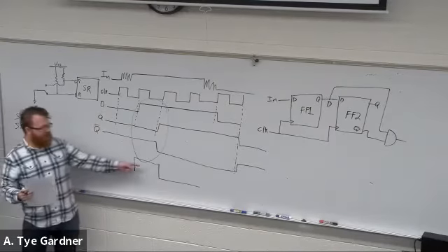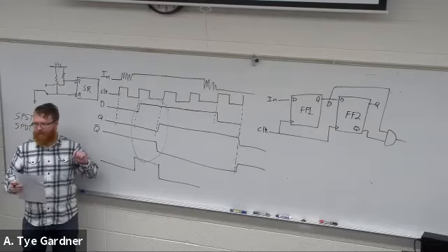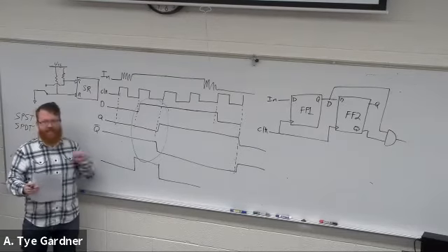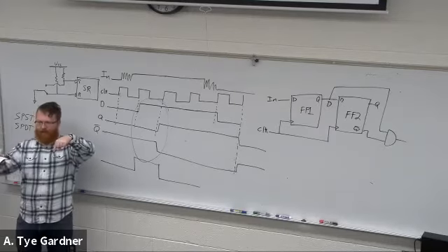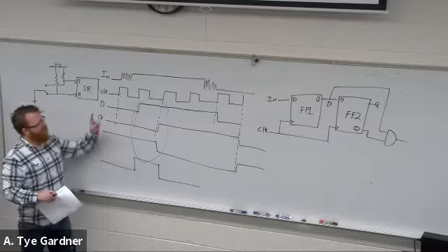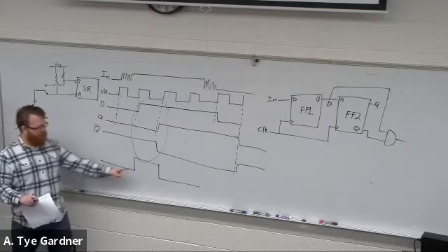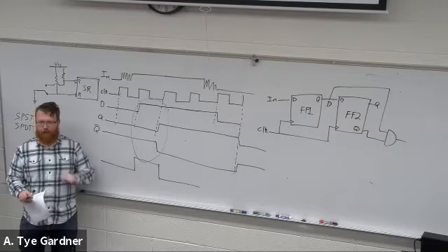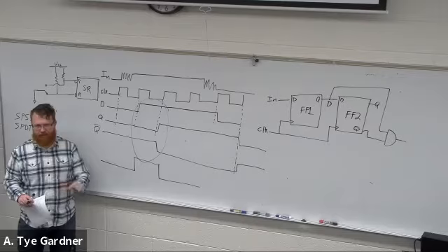So this only detects an edge, right? This is a rising edge detector. Click, sends a pulse, drops, it's done. So you can use the debouncing circuit, which is helpful for problems, to also build a rising edge detector. Make sense, everyone?